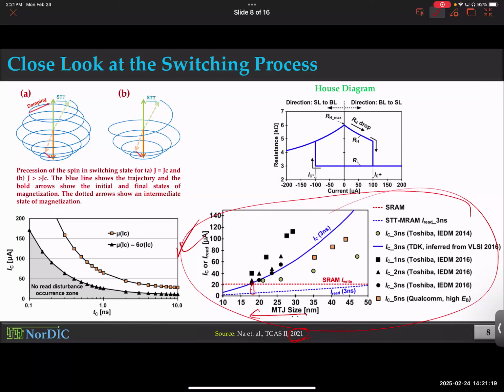So if you are aware of the fact, let me give you a direct example. You're interviewing for, say, Micron, and they ask you, hey, is it better to make the MTJ smaller? Would you like to have a 10 nanometer diameter MTJ or a 50 nanometer diameter MTJ? You say, yeah, it's very good because that reduces the critical current. Done, and nothing else. Is there anything else? So that means it's a clear winner.